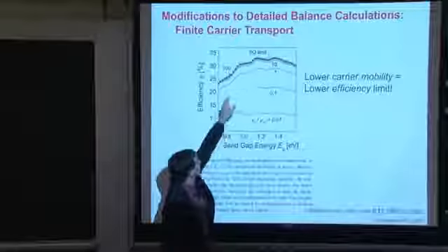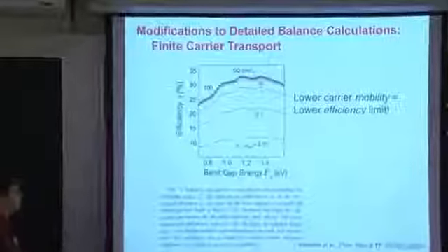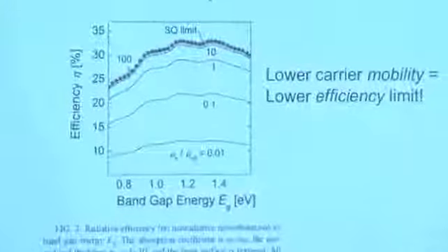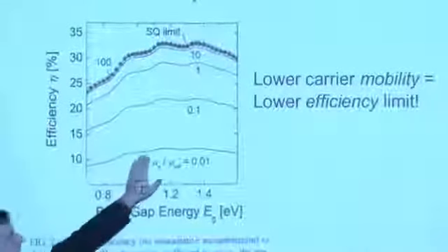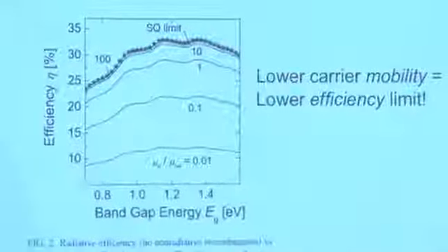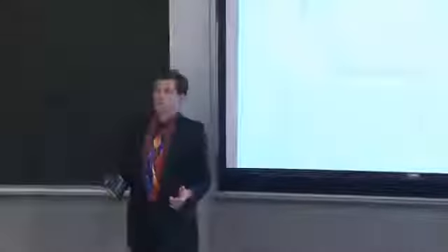let's see, number 1, that curve that's starting here at the 20, that is for a mobility that is close to the optimal. If you drop by an order of magnitude or 2 orders of magnitude relative to, say, the maximum mobility inside of a material, your performance begins to degrade considerably. And now you can understand why crystalline silicon has electron or hole mobilities somewhere in the range of a few hundreds of centimeters squared per volt second. So keep that number in your mind, in the order of hundreds of centimeters squared per volt second hole mobility.